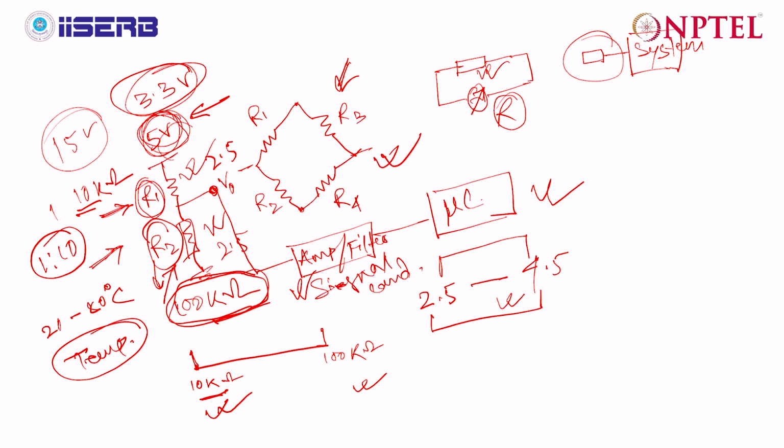But if it's a wearable sensor or a sensor that will draw power from batteries, you have to also take these bias voltages, these resistance values into consideration, so that you can make the system which will draw the minimum power from the battery, and that also will help to increase the lifetime of the entire system, the lifetime of the battery. That means with a single battery you can run the device for say 2 months, 3 months, something like that. So these are the considerations in practice that one has to take care of in both the cases.